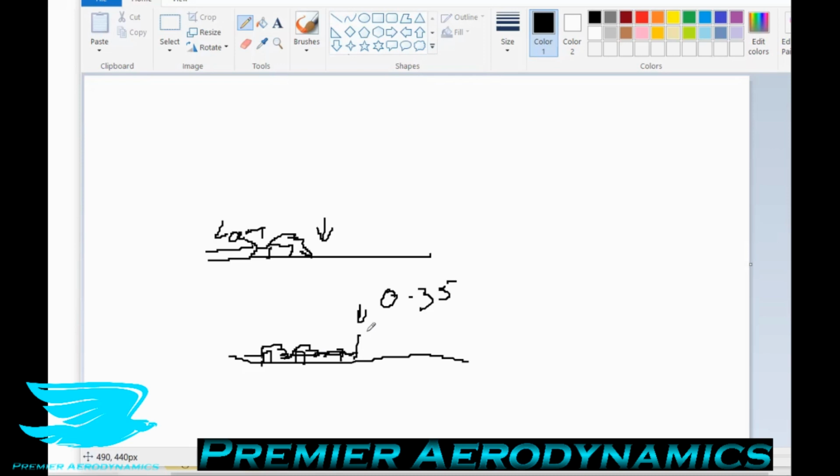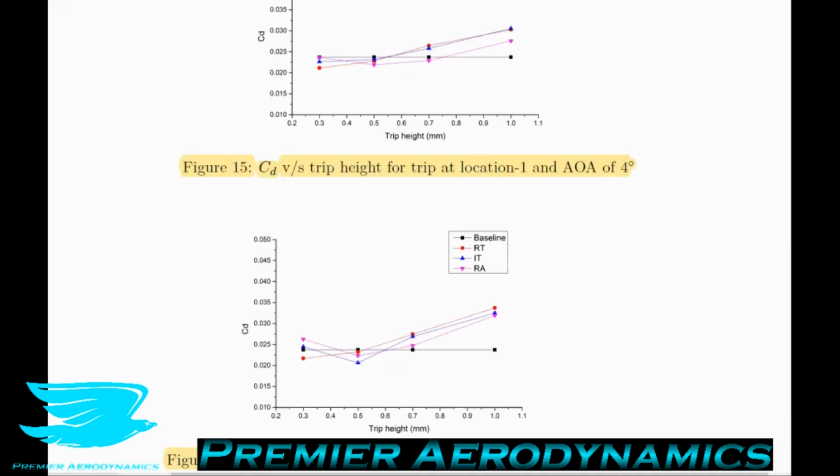It really depends on the Reynolds number and the skin friction, and the roughness of the airfoil, and even the turbulence intensity. But ideally it would, but sometimes it doesn't. So this is where the location of the boundary trip does matter. If it's too far away from the LSB, it won't affect the LSB and we'll still get this increase in drag. If it's close enough, then we will be able to mitigate this LSB formation and we'll be able to reduce the drag of the airfoil. Now, what's more, if it's too big, like let's say it's too high, now we are getting so much turbulence that it's really overkill, and the benefits that we're getting from the boundary trip are not as great as the detriments that we are now inducing because of it.